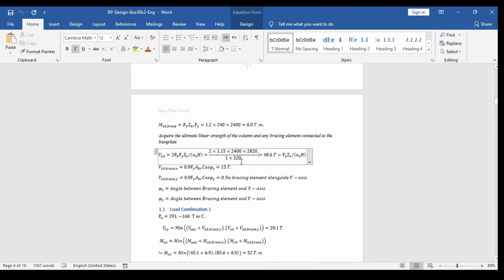Here as well, the shear strength of the column is much bigger than the analysis of the structure due to overstrength seismic load. But likewise the flexural moment, we should add the horizontal component of the axial strength of the diagonal brace to the ultimate shear design force. Just keep in mind, if you have dual axis diagonal braces, you have to consider both of them.